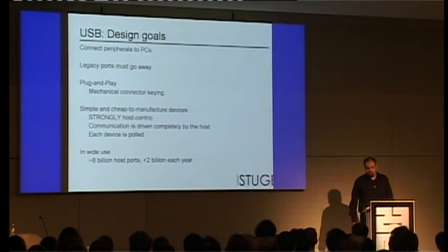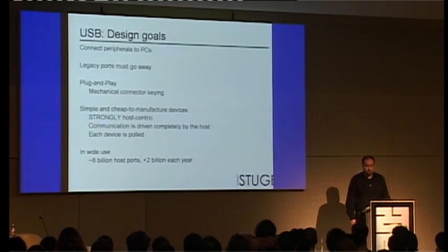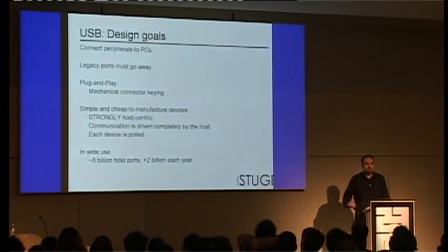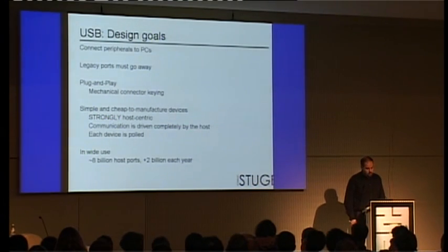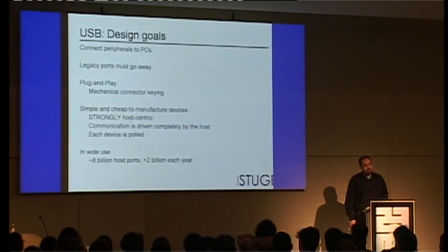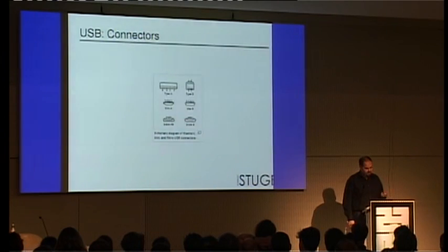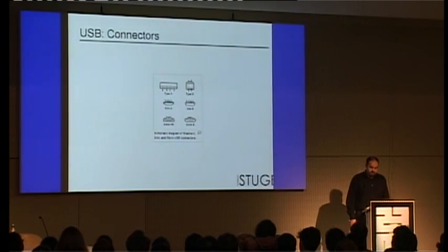Communication is driven completely by the host. It's polled, so the host actually talks to each device in turn and asks it, do you want to do anything? And USB has become really, really popular, 8 billion host ports, and apparently it's increasing with lots of billions every year.